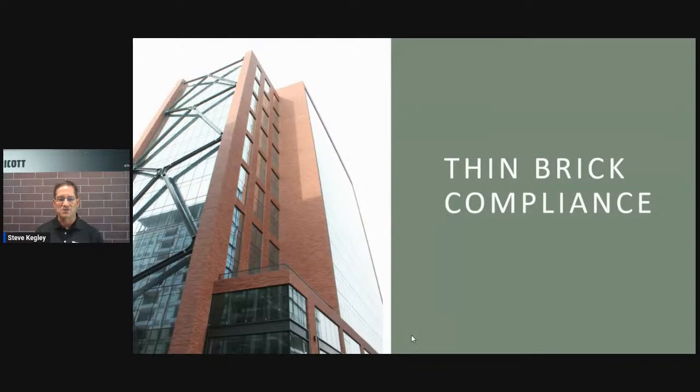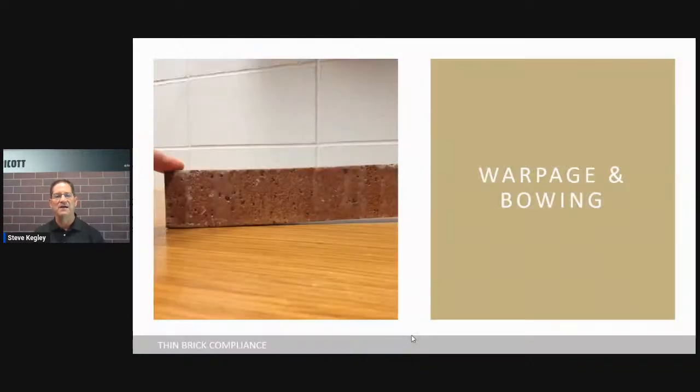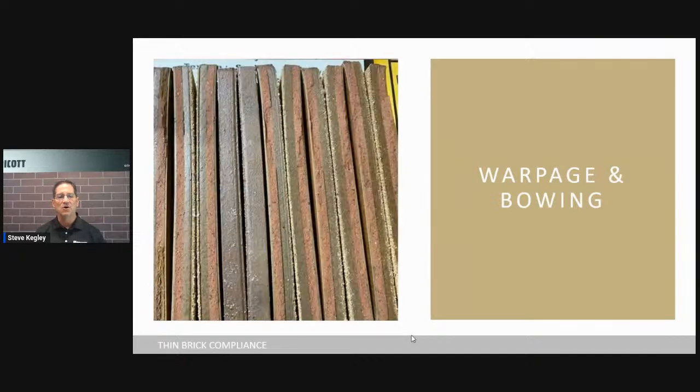So how does thin brick comply with PCI? Okay, this is very typical for anybody, anywhere, anytime when they want to measure a brick. They put it on a table to see if it's flat. Or they lay them back to back. Sometimes they don't even take them out of the packing and they lay them back to back like that so that they can see if they're warped or bowed. And that is not the way to do this.